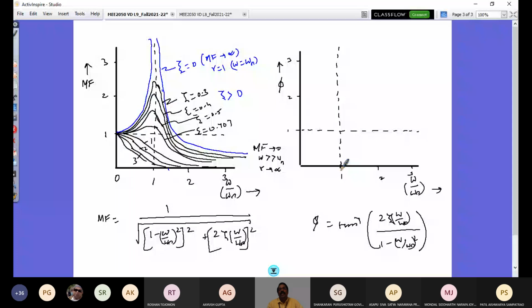That's what you would see in the difference between riding your vehicle on a smooth highway asphalt road and on a rough country road in rural areas. There, the wavelength is more, so the frequency is smaller, and the excitation would be felt more. So what is preferred is that your excitation frequency should be much greater than the natural frequency of the system. This is an application, and it is very beautiful. The basics of mechanical vibration are very important. This is the requirement on the automotive side. So the road should be such that the excitation frequencies are huge, so that you will not have any problem of vibration or other issues.